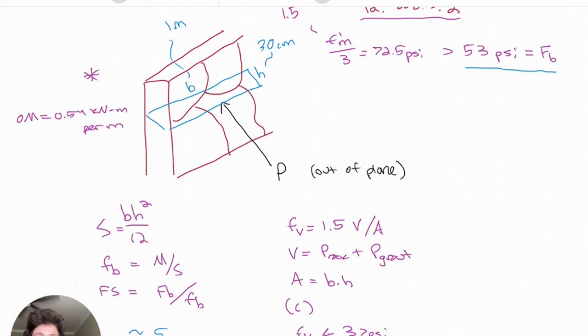So therefore, using our worst case scenario check from before, and assuming there will be some capacity from the soil if it's at ground level, or some capacity from the actual strength of the wall as we move upward, we'll recommend a maximum of 1 meter rise per day in ramp fill.